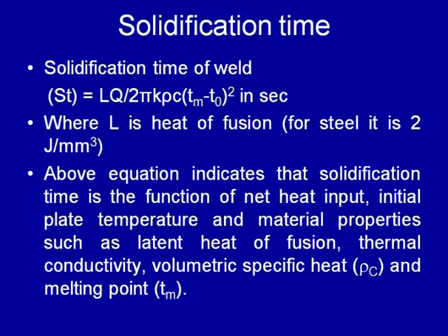So, the solidification time of the weld metal can be calculated using a simple equation: whatever heat is available with the weld metal, divided by the rate at which it is being extracted. So, the latent heat of fusion which is available with the weld metal and the cooling rate, these two are used to calculate the solidification time.